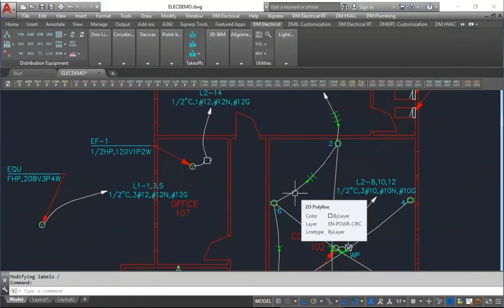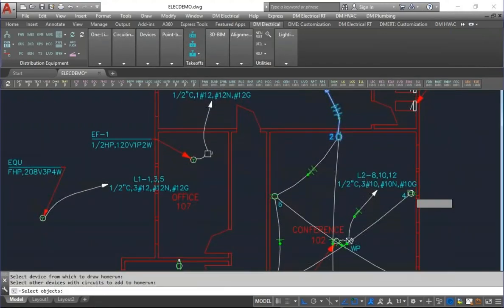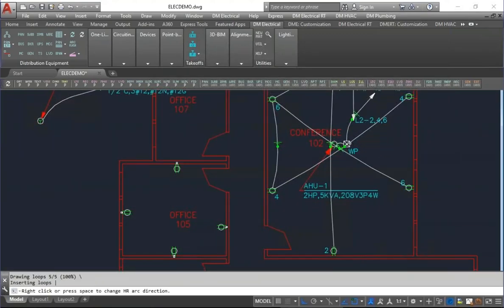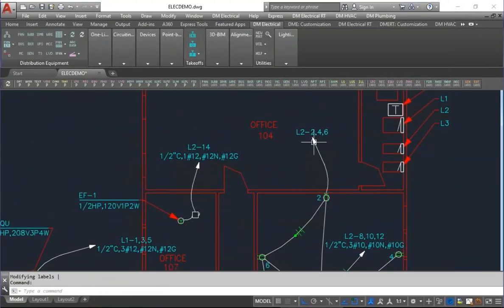It is worth noting that we do not do full wire callouts on combined home runs. So even if you have this set, when you do a combined home run here, you actually, let's see, we end up doing nothing on that. If you have tick marks turned on, it would show the tick marks for the wires on that. And we might list a size. If it's not greater than 12, we'll list a size. So just be aware that combined home runs are treated a little bit differently by the software. We do that just because of the calculations and whatnot that are going on. We don't have a full wire callout once we do the combination.